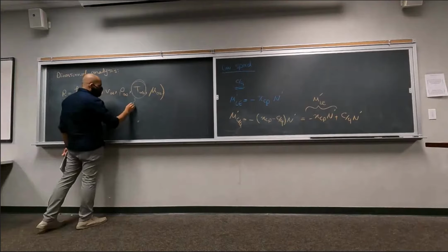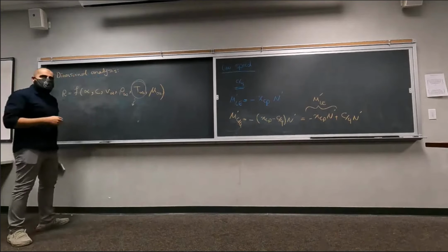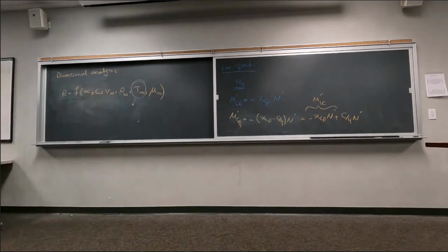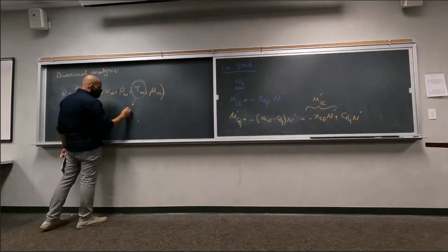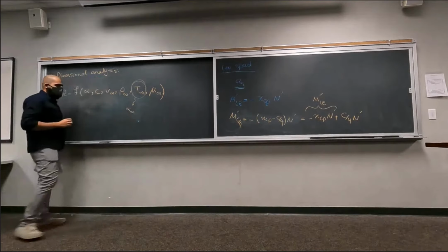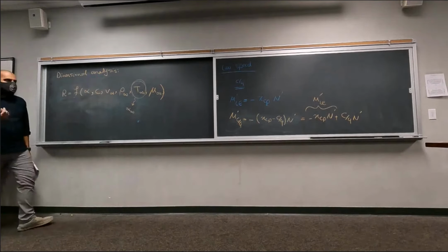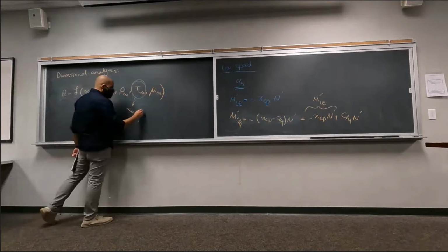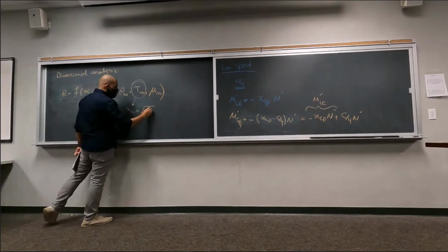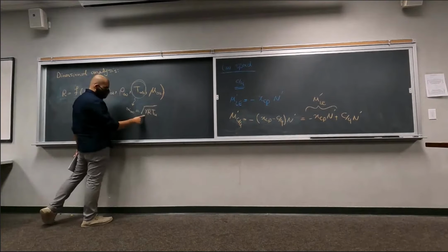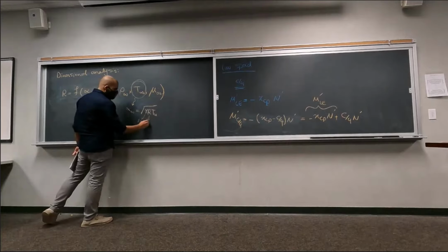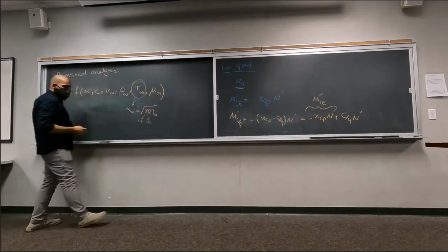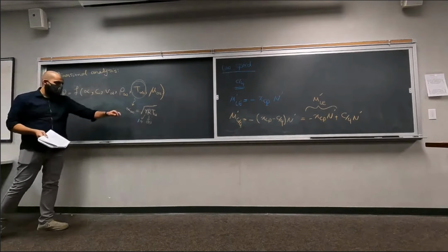But one thing that is important is whether the flow is compressible or not, which can be determined by the free stream speed of sound. Free stream speed of sound is a function of temperature, gamma, R, T, your gas constant, the ratio of specific heat for air, 1.4, 287. That's what we usually do. So that's how it relates to temperature.